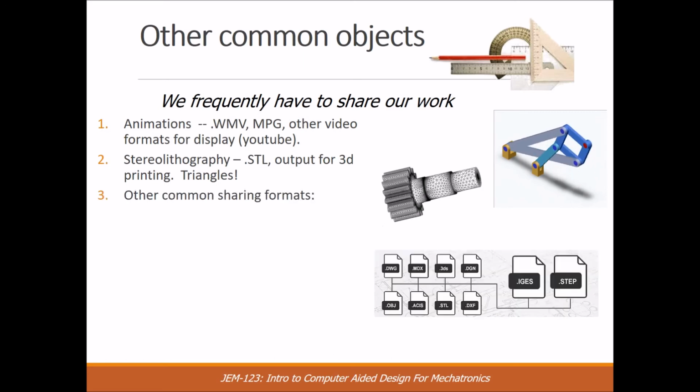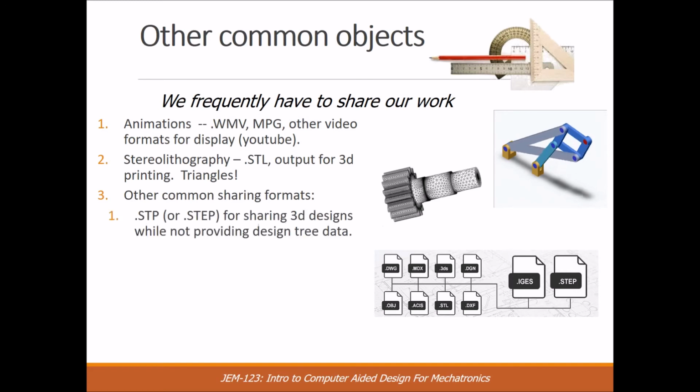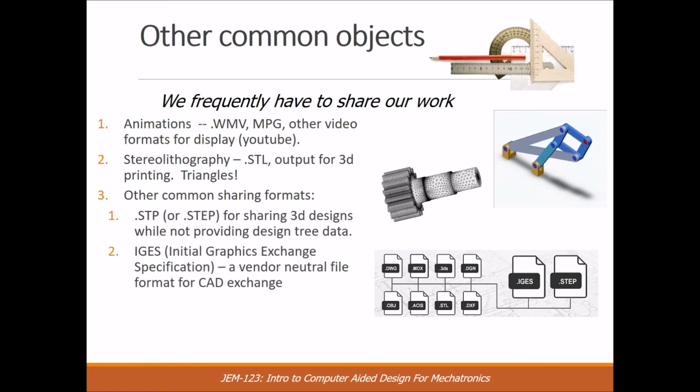There are other formats. There's STEP, IGES, DWG, OBJ, and so on. These different formats are provided so that if you're using a particular CAD product and want to share a file with someone who's using a different kind of CAD program, but one that doesn't understand your native format, this is the universal donor. So if you give them a STEP file or an IGES file, they can then read it into their CAD program.